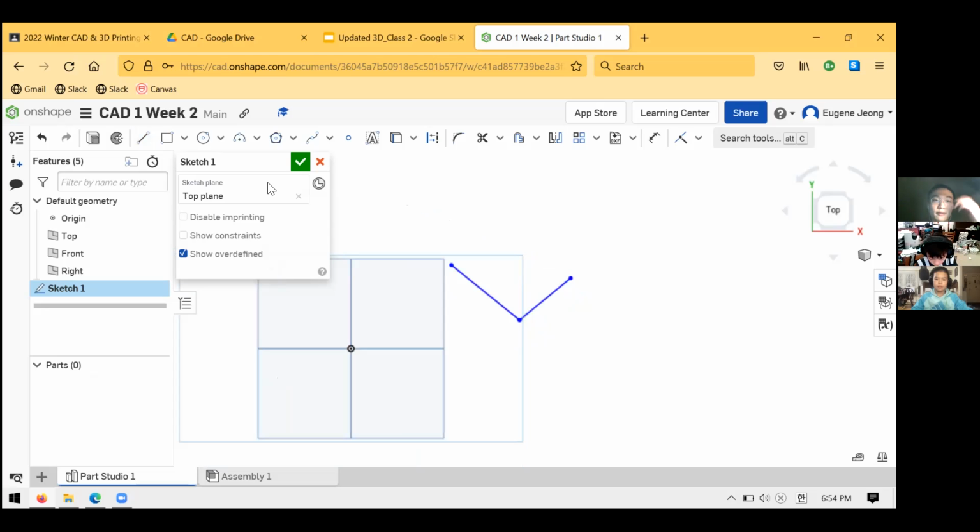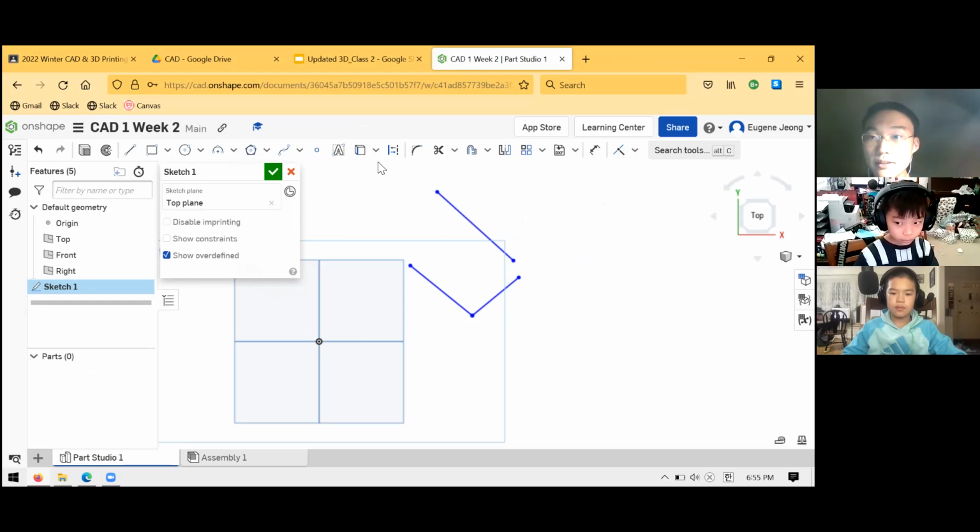So one more time from the beginning, this is called the line to sketch tool, and it allows you to draw lines in your sketch, in your 2D drawing that you're making right now. The way it works, you select the tool by clicking on it in the toolbar once. When it's enabled, your cursor changes, and then you click once, you click twice, you draw the line, and when you're done, you can hit escape, or you can just click on the tool again to deselect it. So that's the basics. You just created your first sketch object, which was a couple of simple lines.